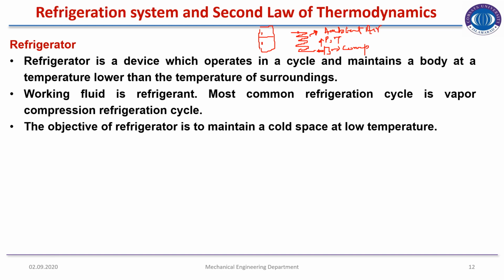And there is an expansion valve, and this will reduce the pressure and temperature, and the evaporator is installed inside the fridge. The evaporator is also a heat exchanger, so it will take all the heat from the cabinet and move it into the refrigerant, and then this is a cyclic process, so this fluid will move back into the compressor.